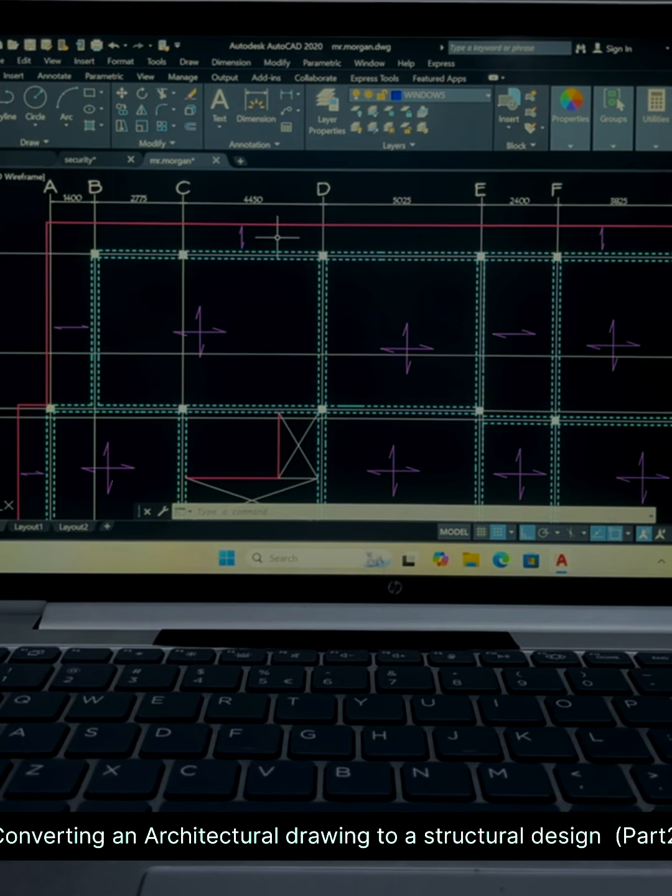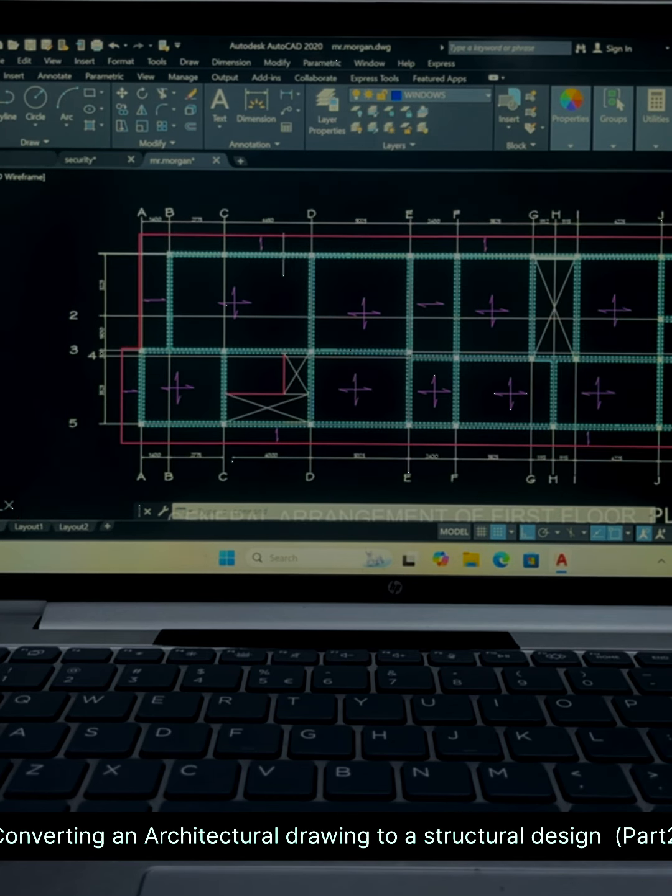Sometimes when you design and the values you assign are not adequate, you go back and readjust them and come back to redesign so that you can get what is adequate for each structural member, like slab thickness, beam depth, column dimension, and the rest of them. But first you must get a general arrangement for everything you are going to do.